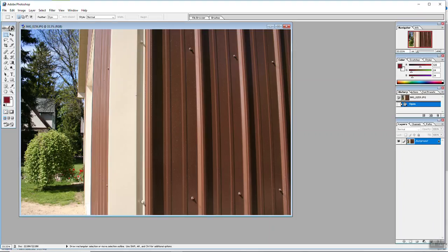Now, this building had an overhang all the way around it. Look how close we got. We lucked out on that one, okay? However, on that 40-foot building, if we'd have started from the left end and worked our way across, that rib would end up right here where that trim's supposed to be, which would really be a problem because you won't be able to take that trim and tuck it up inside the J channel that butts up to the F channel.